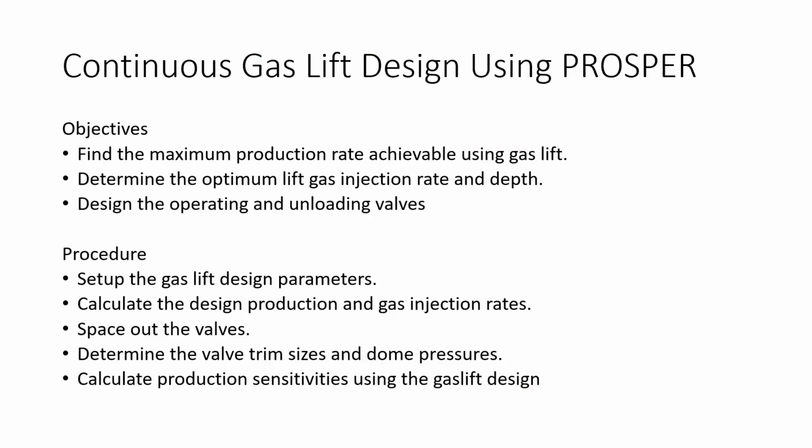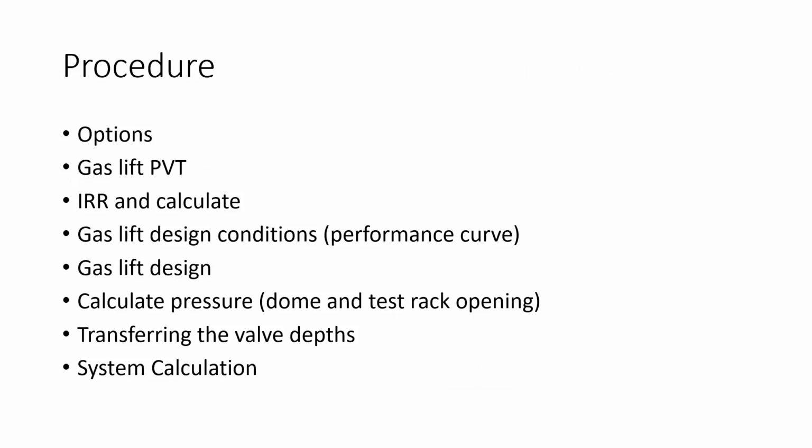Okay, so the procedure is to set up the gas lift design parameters, calculate the design production and gas injection rate, space out the valves, determine the valve trim size and dome pressure, and calculate the production sensitivities using the gas lift design. Okay, so these are the procedures.